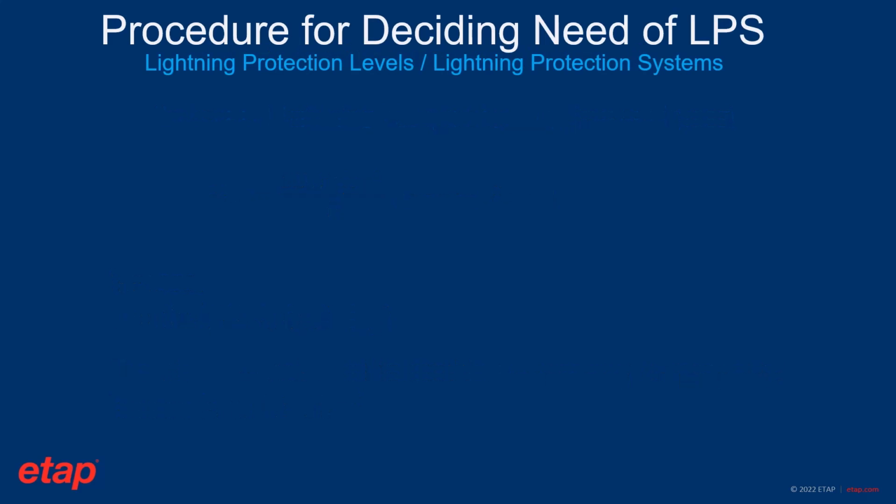Now, once we determine NC and ND from the previous examination, we have a clear flow on how to perform the surge protection to be installed on that particular system. It has been broken down in IEC 62305 as a step-by-step procedure using this particular flowchart.